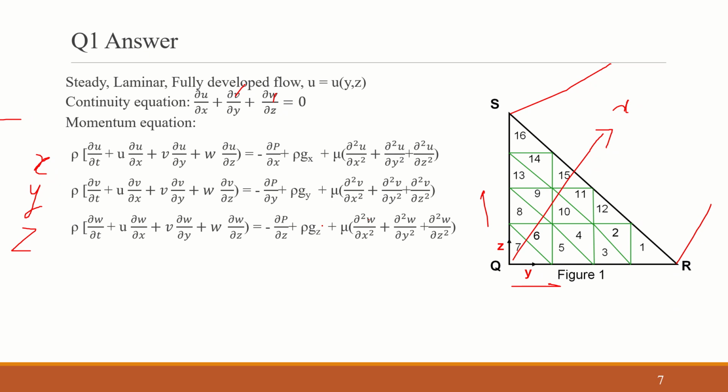In general, for a cold flow system, cold flow in the sense that there is no external energy transfer inside the system, these are the four equations that we will be solving. First is the continuity equation, and then the x component, y component and z component momentum transfer equations. So three momentum transfer equations and one continuity equation we will be solving to obtain any solutions.